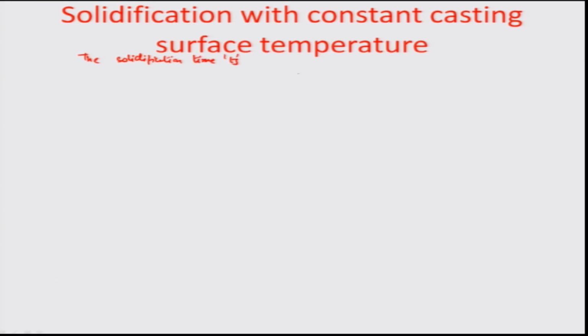Ts. So we get that delta at Ts should be really equal to half the thickness of the casting. We assume the casting thickness here to be equal to h. So therefore there is heat transfer from both sides of the casting. So therefore h by 2 is really the plane along which the solidification fronts from both sides would propagate and stop. Okay. So the temperature profile